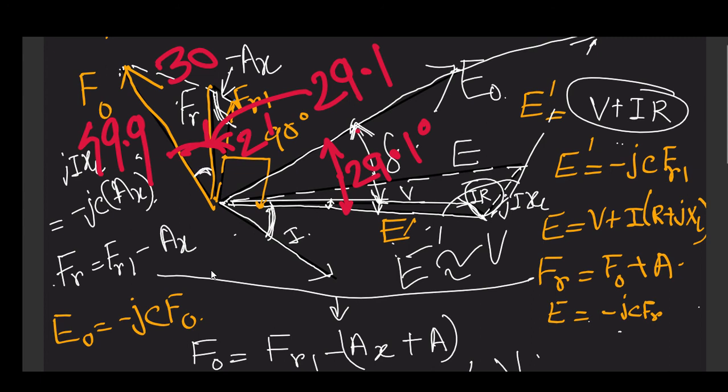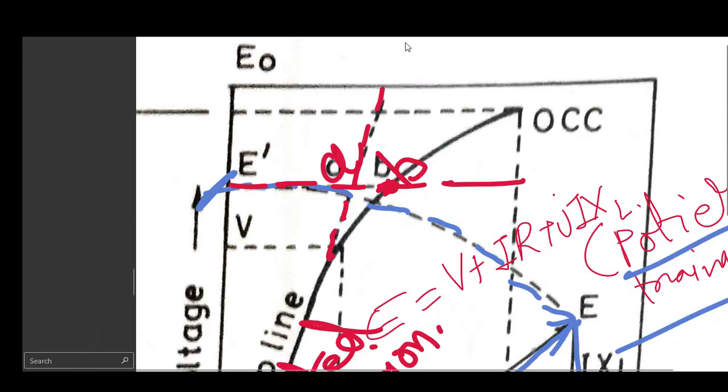Now in zero power factor method we can find out the angle between this. This is coming 7.5. Now obviously, for the corresponding value of E naught it is 90 degree, right? And E is 90 degree with this one. So from this we can say that the angle between E naught and E is 7.5 degree, right? So therefore